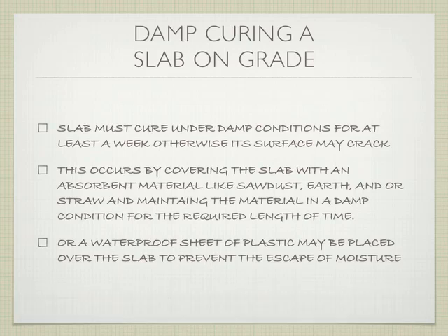So if we're going to cure a concrete slab, and we talked a little bit about this before, the slab needs to cure under damp conditions for at least a week. Otherwise, the surface itself may crack. And so if you're around a slab and you look down and there are no little fine hairline cracks, you know that they cured it under damp conditions. If the surface dries out too quickly, there's going to be a network of cracks that will appear just in the surface, and it won't look as good.